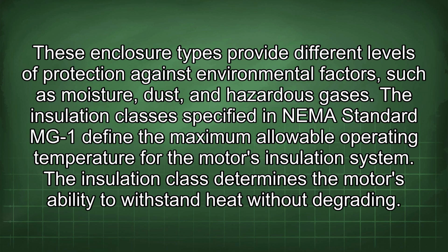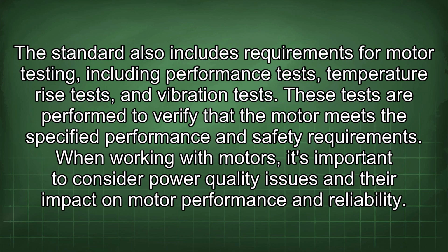The insulation class specified in NEMA Standard MG-1 defines the maximum allowable operating temperature for the motor's insulation system. The insulation class determines the motor's ability to withstand heat without degrading. The standard also includes requirements for motor testing, including performance tests, temperature rise tests, and vibration tests. These tests are performed to verify that the motor meets the specified performance and safety requirements.